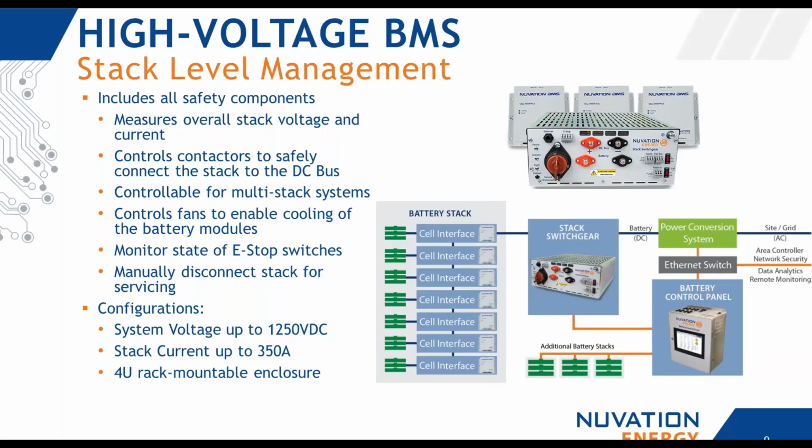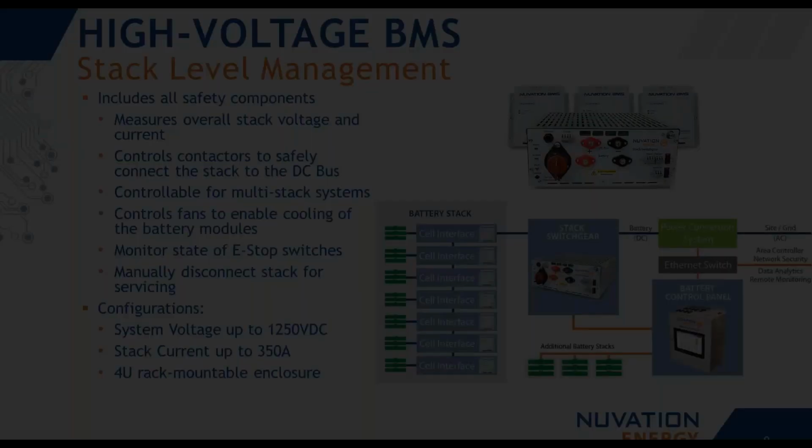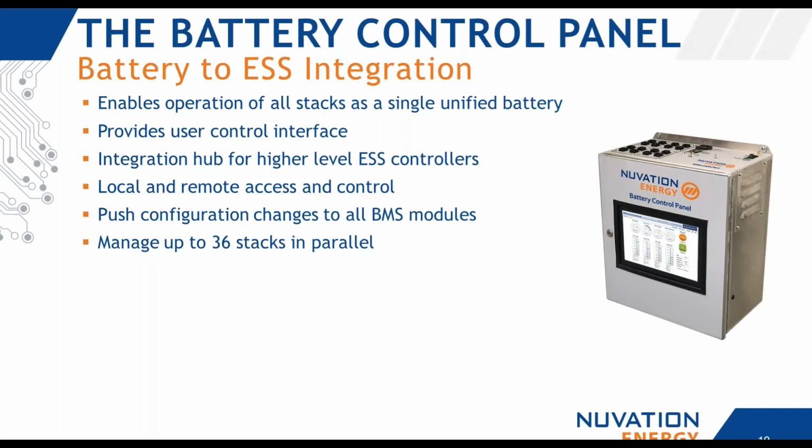Our battery management system comes in multiple layers. We have the cell level and stack level controllers. This includes all of the functional safety aspects around controlling batteries. Then at the higher level, we have a battery control panel.